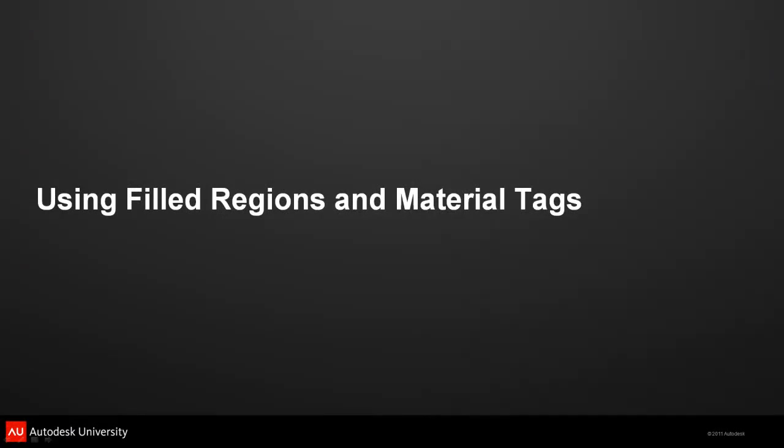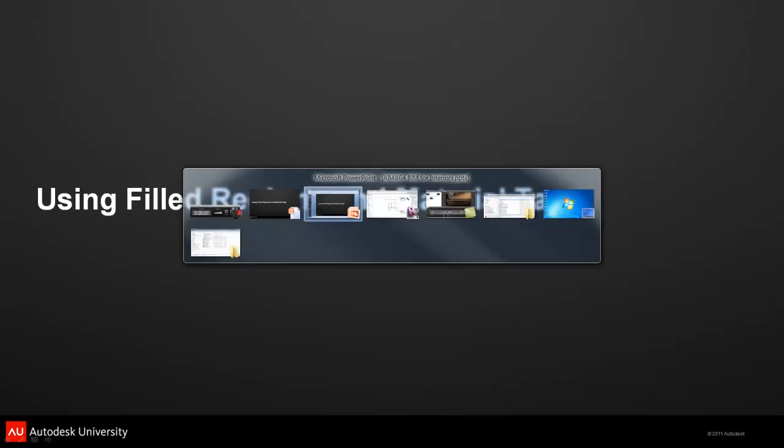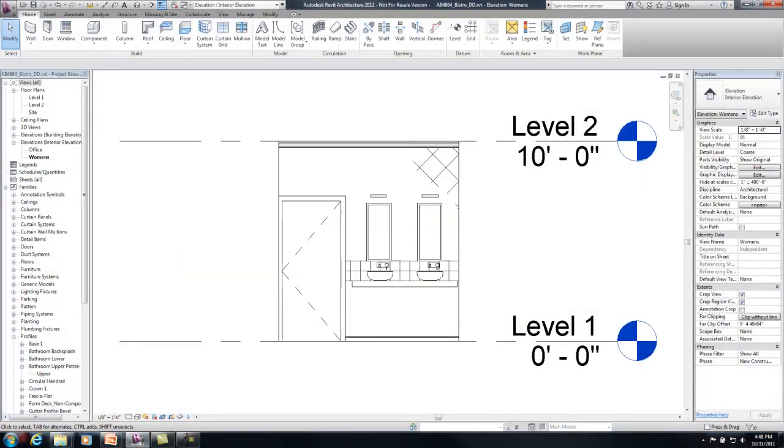Let's discuss using filled regions and material tags in interior elevations. Here in our bathroom interior elevation, we can see that we have a filled region in the upper right-hand corner to represent a pattern on this wall. Material tags are typically used to call out the materials on walls, especially when there are multiple materials being used.